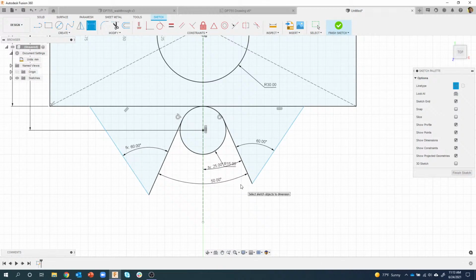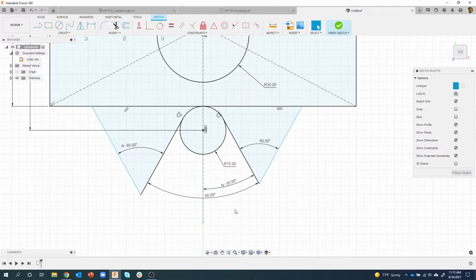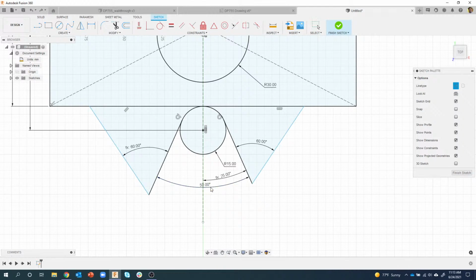And notice what happens. Let me kind of move this down a little bit. It now says 25, and you can see that those two blue lines became constrained, and they look nice and even now. We obviously know this is 25, so that has to be 25. And again, because we're referencing this, if we were to change this to 60, that would have to be 30. So try not to type in the numbers as much as referencing existing ones. That way, if you come in and change them, they'll update accordingly. Hopefully you guys knew about that tip.